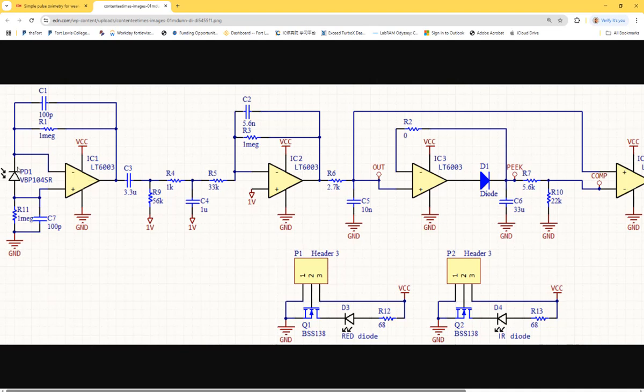What is this guy? It's a light emitting diode. Hmm? No, it's the other way. So what is this guy? It's a photodiode. It's an IR light receiver, right? It's an IR light detector. It's being reversely biased, which means all the photodiodes are reversely biased when connected to the op-amp. So it's converting the current to voltage, right?